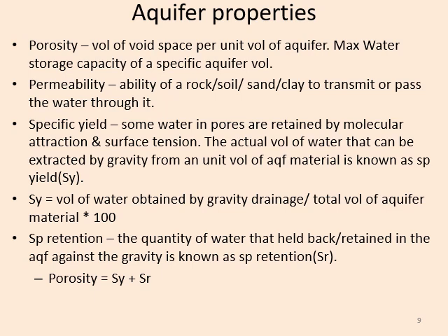Specific yield. Some water in the pores is retained by molecular attraction and surface tension, as we have seen in the first 2-3 slides. The actual volume of water which can be extracted by gravity only from a unit volume of aquifer material is known as specific yield, and it is denoted by SY.